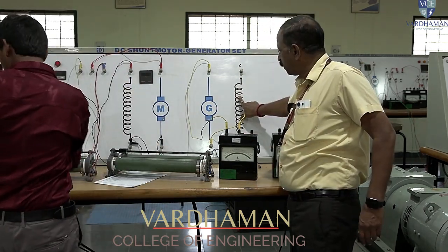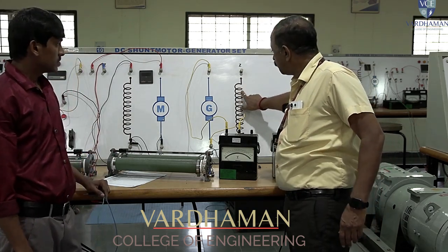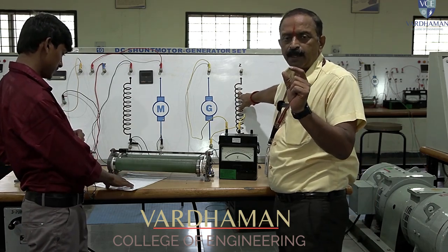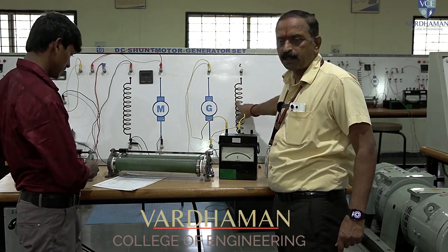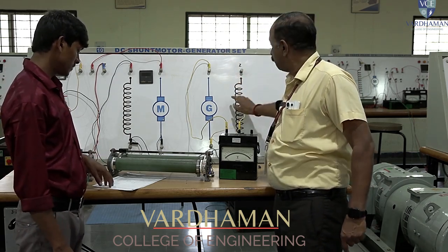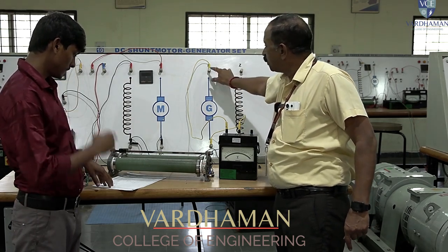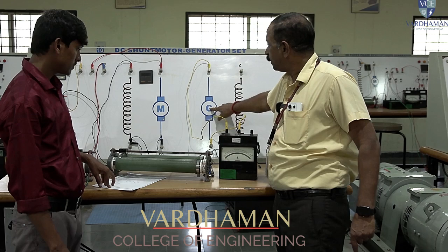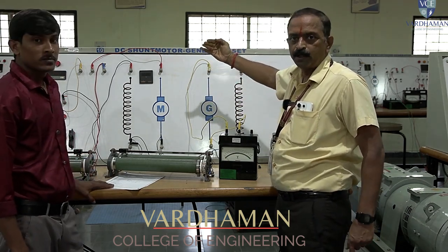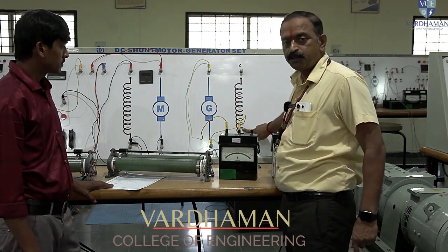Even though it is an iron piece, it is not a magnet. The current makes the iron piece behave like a magnet. Initially, it has a residual magnetic property, an inherent small amount of magnetic property in the iron piece. Because of that, a small amount of flux will be released. Even though there is no current flowing through this, because of that residual magnetic property in the iron piece, a small amount of voltage is initially induced. That is the reason in this experiment you can see the graph will start a little above zero voltage. Initially, only at the 0 position, the voltage will be induced because of that residual magnetic property.